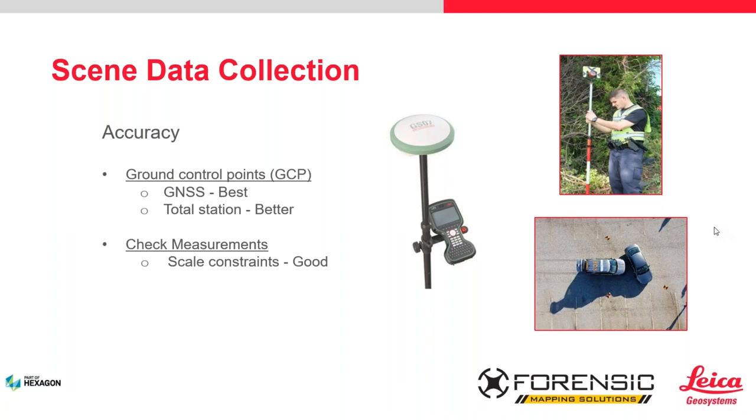So how do we do this? It sounds like a lot of you indicated in the poll that you were using a total station. So let's go through this. The most accurate and best way to do it is to use the RTK GPS. The reason is that it is going to give us position in X, Y, and Z to a couple hundredths of a foot, in what's called state plane coordinates. State plane coordinate is a coordinate system in which every place has an exact position. So if we have evidence or media in state plane coordinates, it will all be able to link up together in different software that you're using, like Map 360. That allows you to have a common coordinate system.